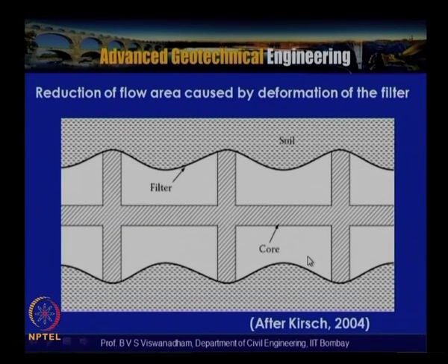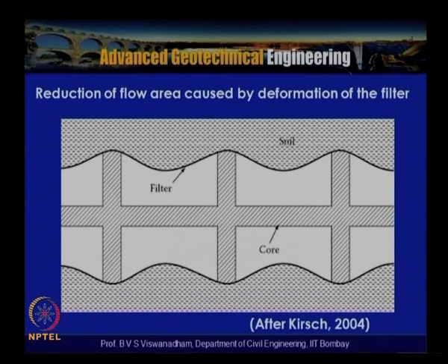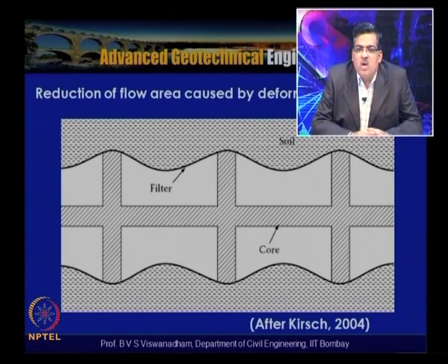addition to that, if these elongation conditions are clubbed with this, then there is a possibility that it will get affected. The reduction of the flow area caused by the deformation of the filter can be seen from this slide. These conditions hamper the flow conditions through the flow channels, which in a way affect the performance of a PVD installed site.